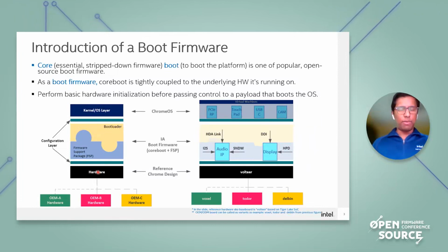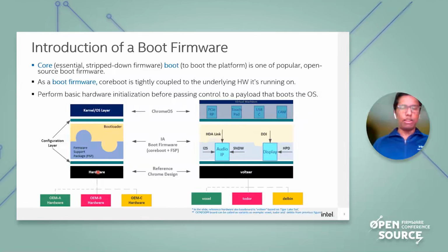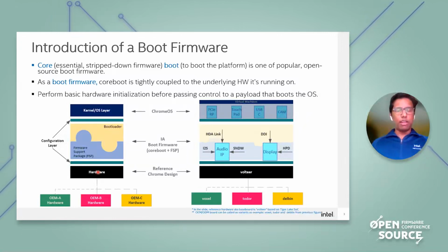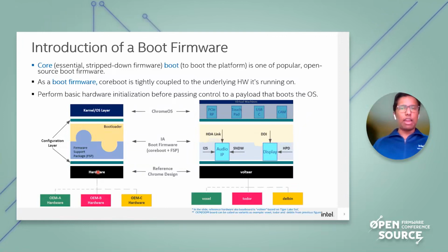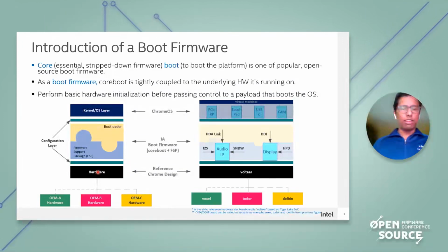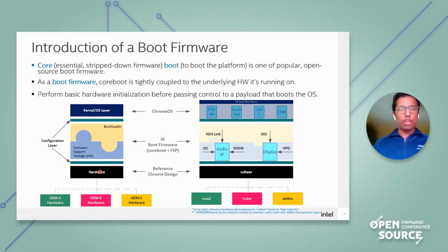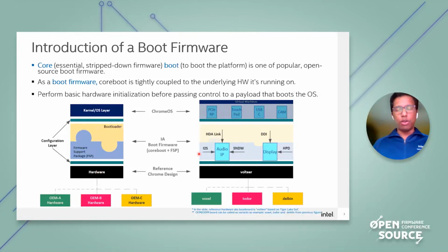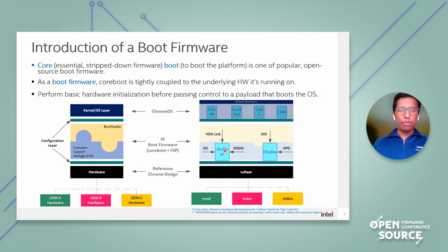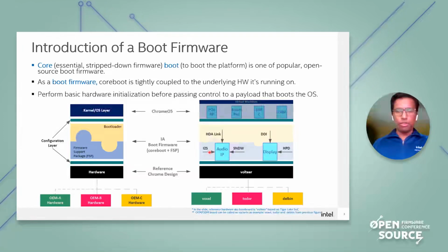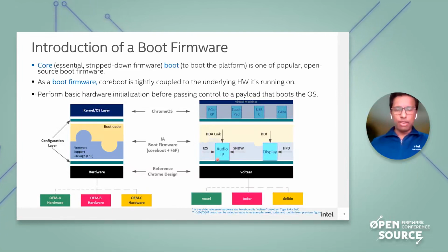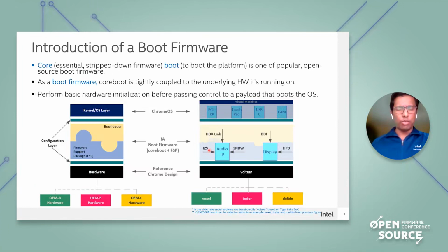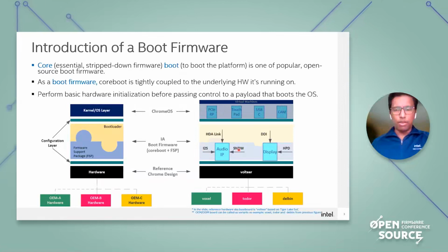A single hardware component may have different possible interfaces that the firmware or bootloader is supposed to configure, to find the exact hardware interface that satisfies different ODM and OEM needs. Take the audio IP, for example. Audio can be configured in any of three interfaces: HDA, SoundWire, or I2S. Based on the final design, an ODM or OEM may be using I2S, or somebody may be using HDA or SoundWire.